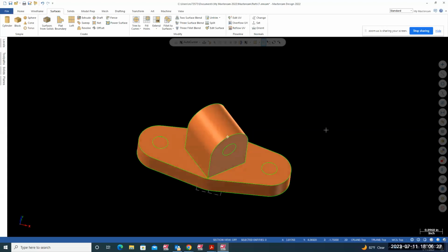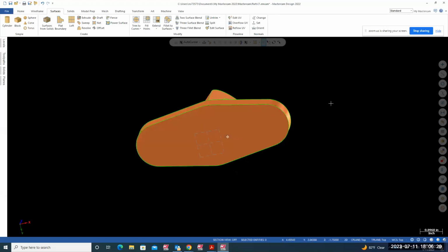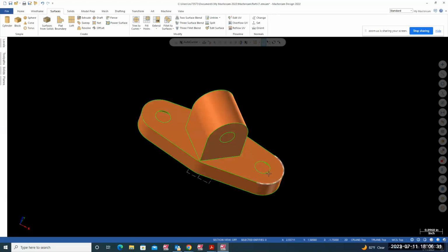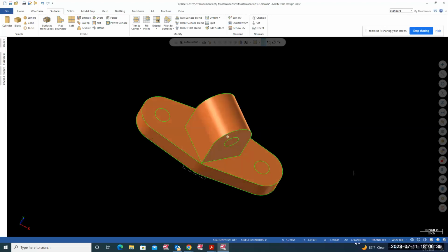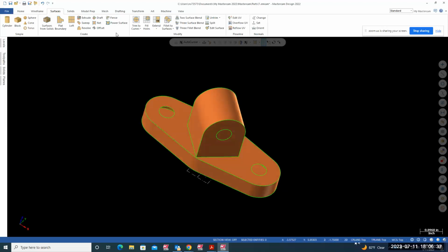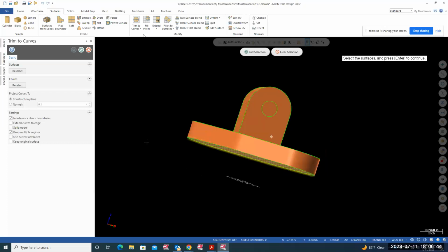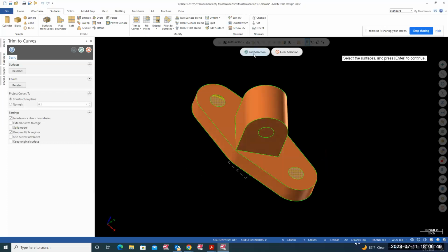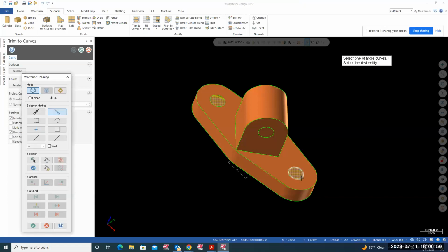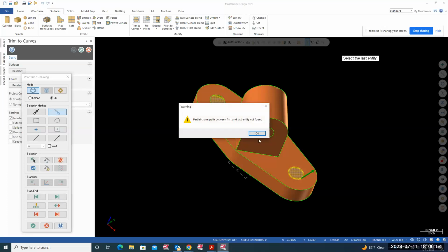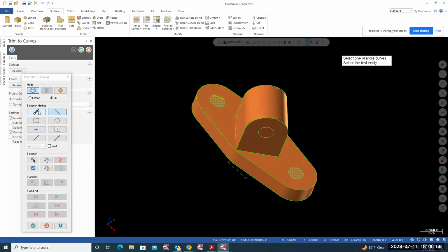Now, to make a hole through, I can trim that surface through that curve because it has to be in construction plane top. We are in top plane. So I can go ahead and say trim to curve. I want to trim this surface, and selection. And curve one, this is my curve one, this is my curve two. Oh, sorry, it has to be chain over here, guys.